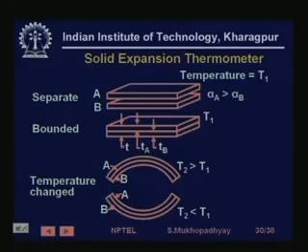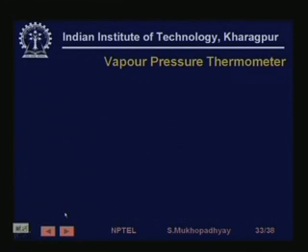So, at one temperature they have no stress among them and they are bonded together. If temperature decreases, it will turn one way, if temperature increases, it will turn the other way, right. So, from this motion we can measure temperature, and there are industrial sensors which actually utilize this kind of bimetallic sensor. They are sometimes also used for temperature switches, and sometimes as bimetallic springs. As the temperature rises, the spring rotates and it can be connected to something like a dial.